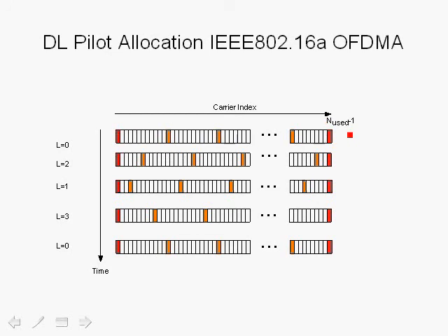So for example, here we're sending one OFDM symbol which is made up of 2048 points, but here we're only focusing on the N used points because we're only interested in the data carriers and the pilots, ignoring all the other carriers, for example, the null carriers in the left and right guard intervals and the null at DC. So in this case, N used is equal to 1702 carriers.